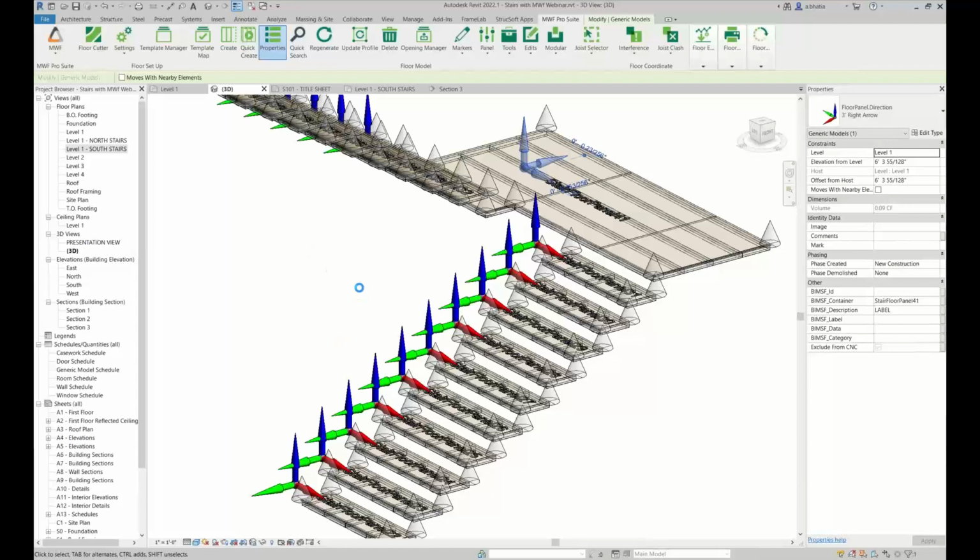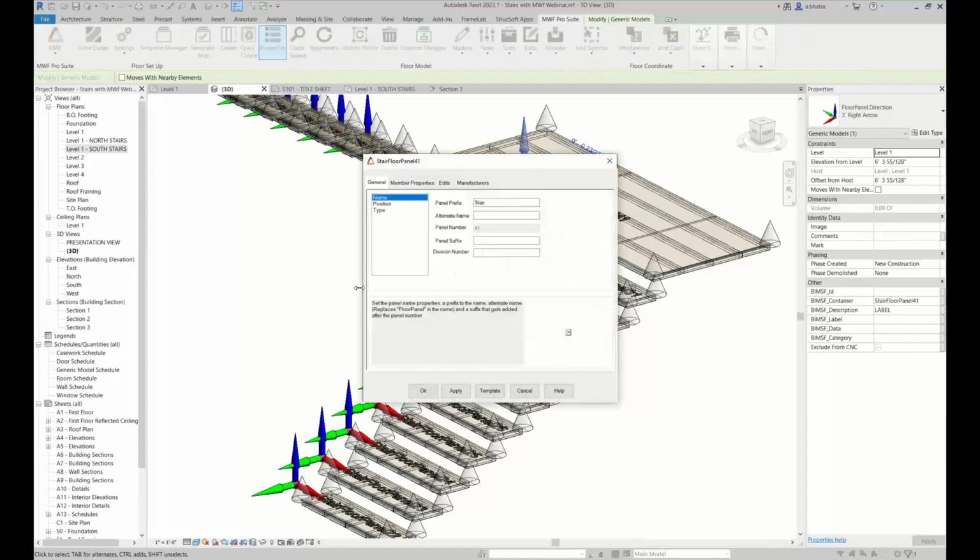Since your stairs can be located and oriented in multiple different ways, I prefer to rotate it with the widget. But if you knew exactly how your stairs are going to be located in the entire building, you could always set the position up to be correct and set your joist rotation to be accurate as well. So here for the position, I've set the member reference to bottom, structural face bottom as well for alignment layer. I don't have any openings in here, so that doesn't really matter.